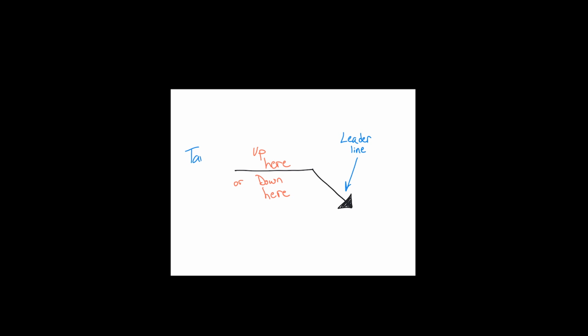And I didn't draw it before, but there's also a tail section to the reference line. And you'll find any sort of additional notes in here that cannot be drawn as a symbol on the reference line. This can be stuff like what type of welding process you're supposed to use, what type of electrode you need to use, or basically any other additional notes that you can possibly think of that cannot be drawn as a symbol.